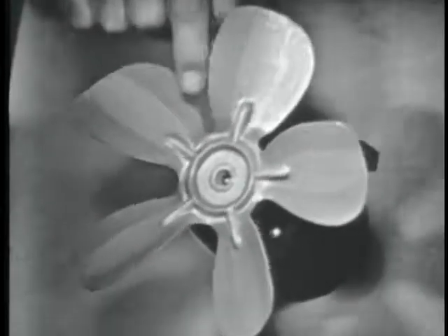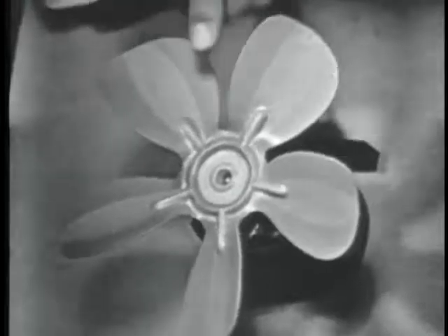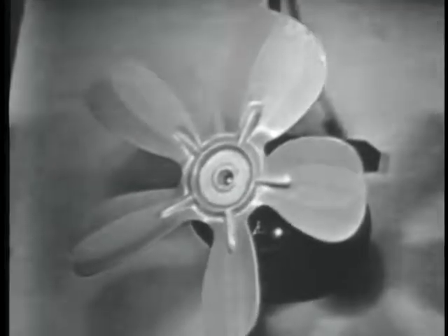Very good. Now, when we put this fan blade on the rotor, we have increased the load or the drag on the motor. And therefore, it's going to turn a little slower. In fact, I've got to give her a little start there to get it going. Now, it turns slower. Before, the rotor was turning almost as fast as the magnetic field, under a no-load condition, of course. Now it slows down a little. Well, it slows down a lot because it's got work to do. There's more drag on it. So the rotor does then turn slower than the magnetic field. I think we've proved that point, Bob.